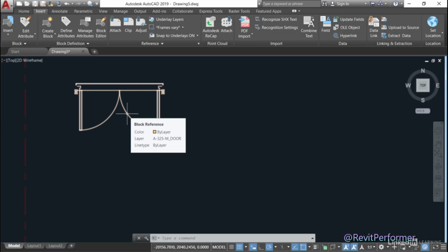That's the important thing, because these objects now are going to be in a drawing that you may use to bring across into Revit as a linked CAD file or as an imported CAD file, which means they're on the right layers and they're adhering to the AutoCAD standards that you set originally. That's the really important bit. So you're making sure that these drawings adhere to the right standards before you even consider linking them or importing them into your Revit projects.